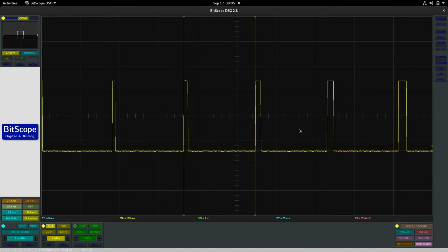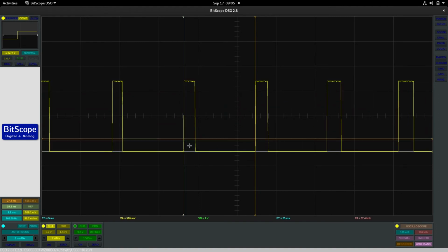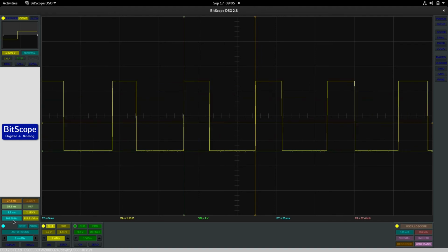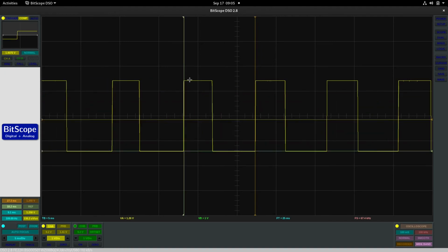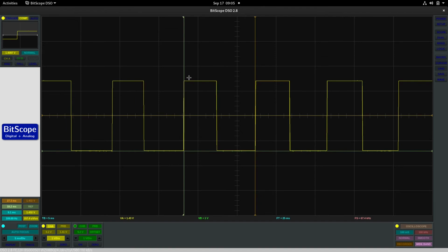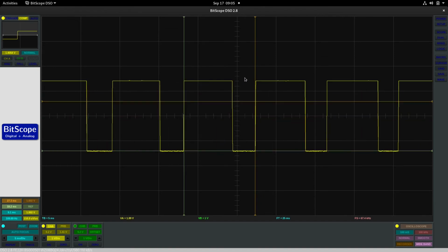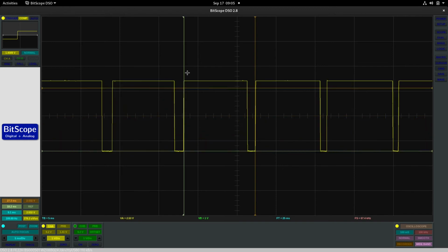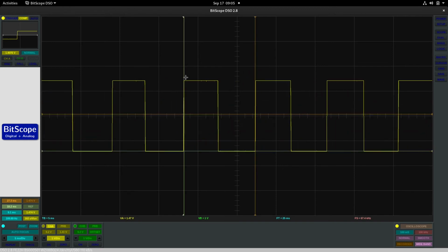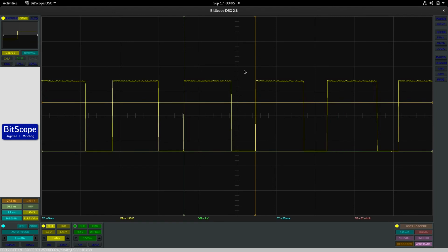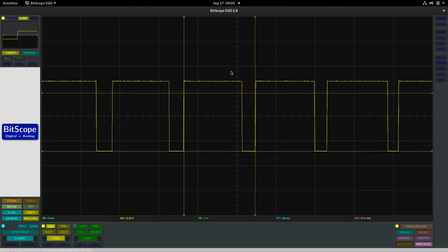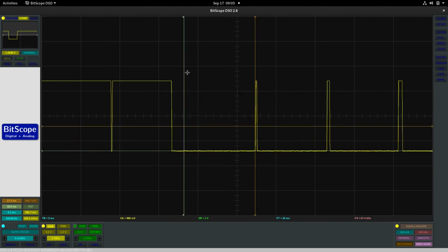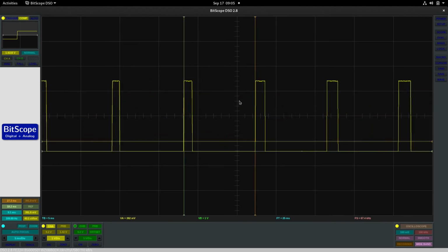Let's have a look at our scope to see what's going on with the signal. Again, we have the same, close to 100 Hertz frequency. And if you look at our duty cycle, it's changing from 0 to close to 100, and then it's jumping back. So we want it to travel back and forth, from 0%, go to 100%, and come back slowly from 100% back to 0 instead of just jumping right back into 0 from 100%.